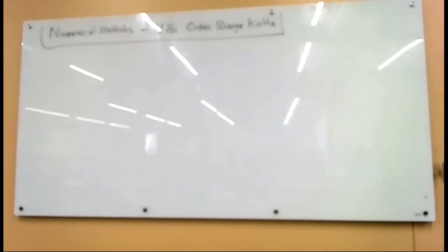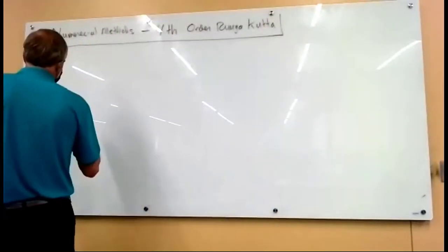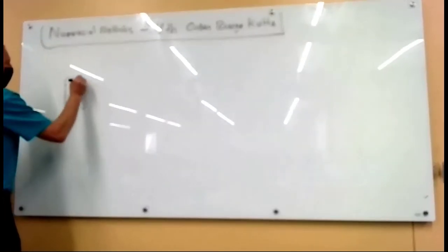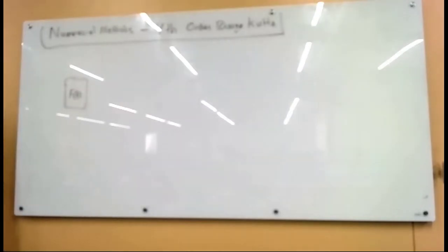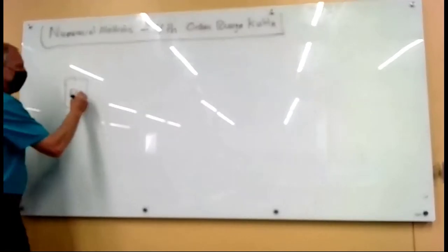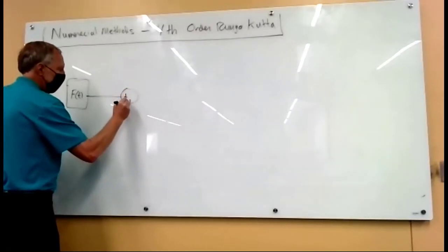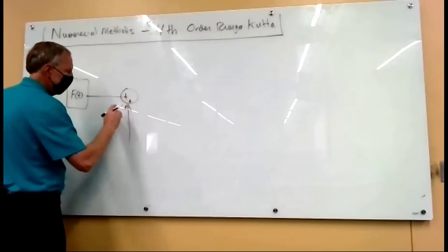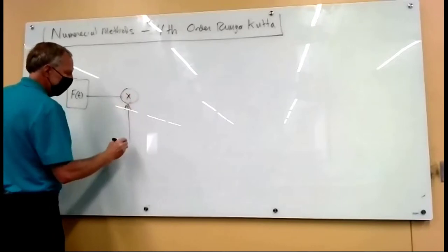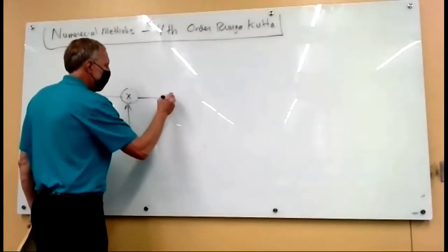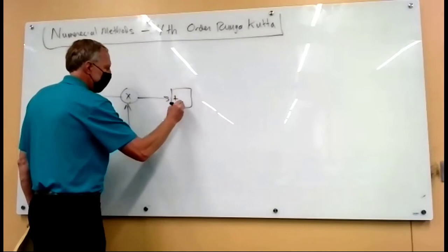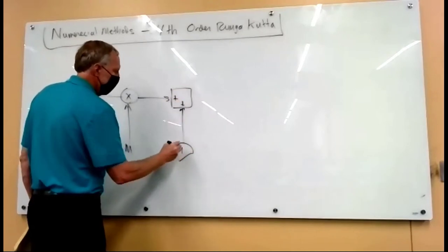No, in MATLAB. It's really a way to do block diagrams that do calculations. Like if you have a block in it that would say create a signal f of t, that force signal for our mass, and then you can send it through a product where you would multiply by the mass, and then you could send it through another block if you wanted to, where you could add the number 1 to it.